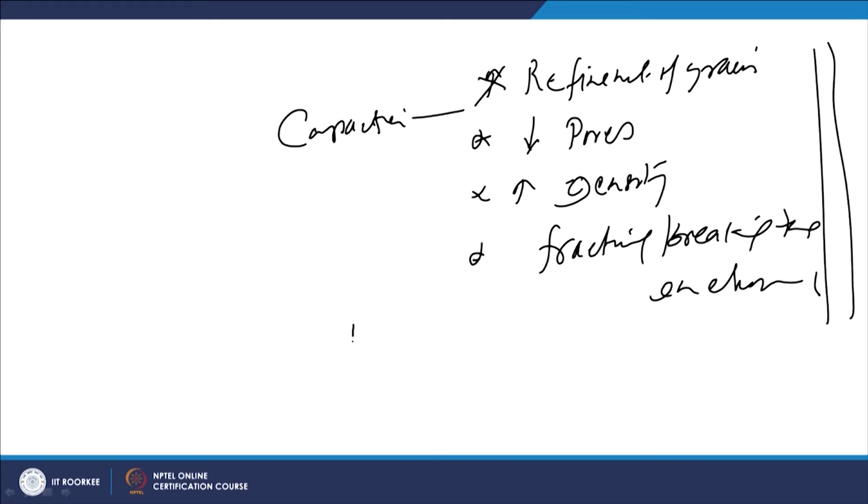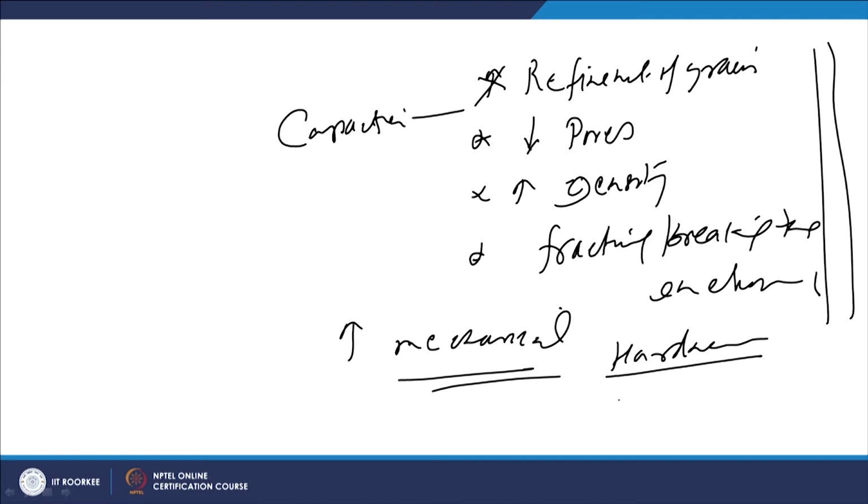All these factors are expected to enhance the mechanical properties, and in this particular case, due to the refinement and elimination of the pores, a 30% increase in the hardness was observed, and this in turn also led to a 30 to 40% improvement in wear resistance due to the compaction.